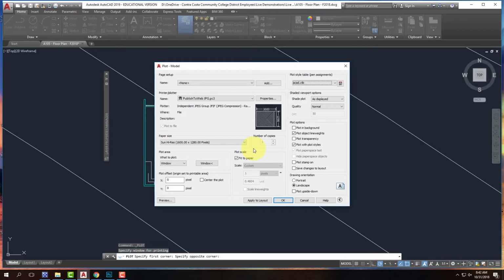Anyway, for our purposes, we're not assigning line weights by color. That's something that you can learn in a firm. The other thing is firms always do it different. So you go to work for one firm, line weights look different than another firm. It's annoying. Anyway, for our purposes, we're sticking with just basic what you see is what you get, which the AutoCAD CTB, the default, is perfect. That's what we want. So that's on.